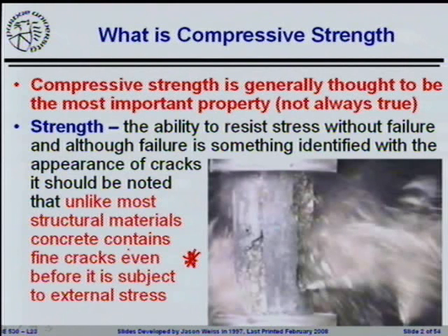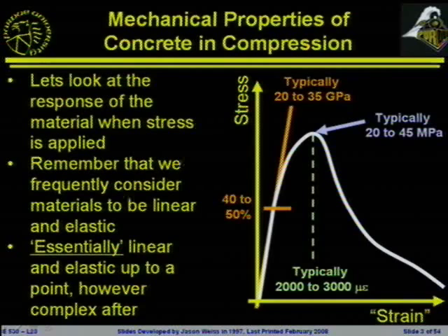And a lot of people will say, oh, my concrete's cracked. Is it a problem? Well, almost every concrete that's put out is reinforced concrete. And I will tell you that if your concrete doesn't crack, you could have saved a lot of cash by keeping the reinforcing to yourself. Not putting the reinforcing steel in there. Because until the concrete cracks, the reinforcement doesn't do a whole lot. The real value of the reinforcement is when the concrete starts to crack.